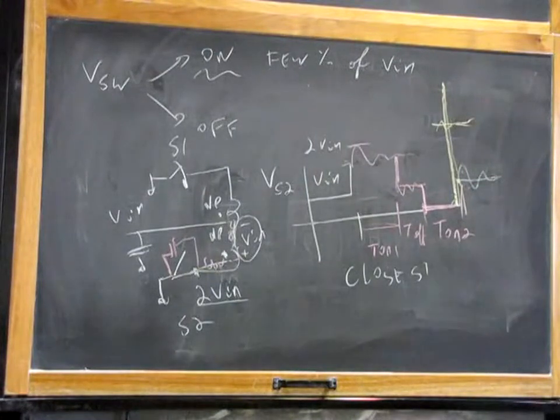You can use clamps, Zener diodes, high-speed Zeners in this application. You don't use standard Zeners. You use specific components. They are basically Zeners, but designed for this application. They are able to absorb a very large energy for a very short time. And those are called transils or TVS, transient voltage suppressors or things like this.